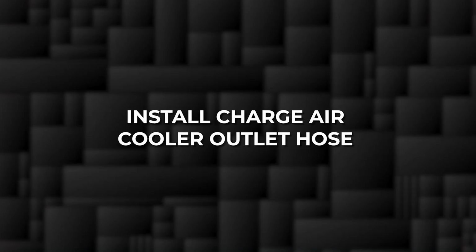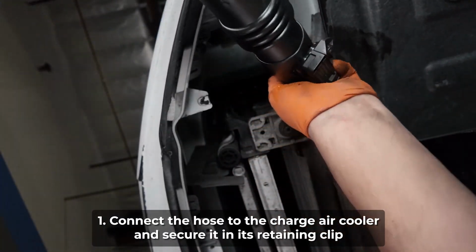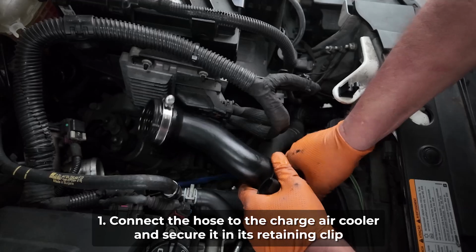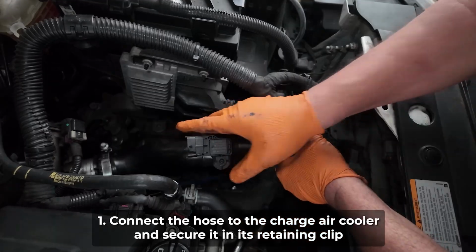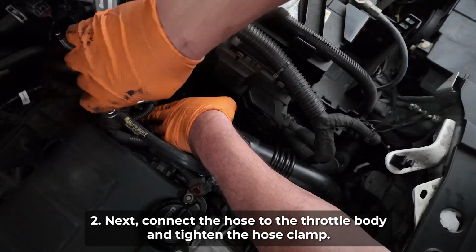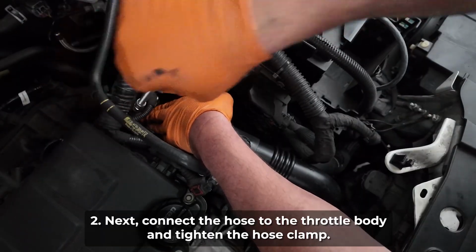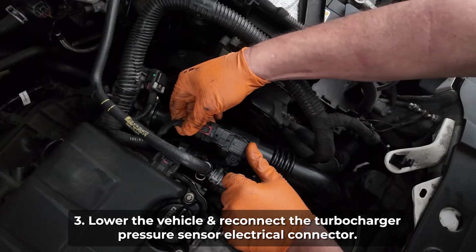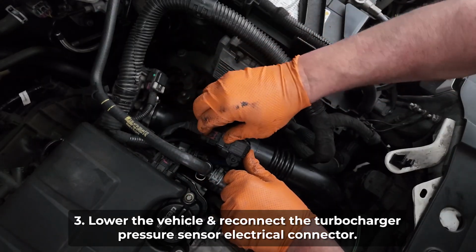Let's install the charge air cooler outlet hose, the cold side intercooler hose. 1. Connect the hose to the charge air cooler and secure it in its retaining clip. Next, connect the hose to the throttle body and tighten the hose clamp. Lower the vehicle and reconnect the turbocharger pressure sensor electrical connector.